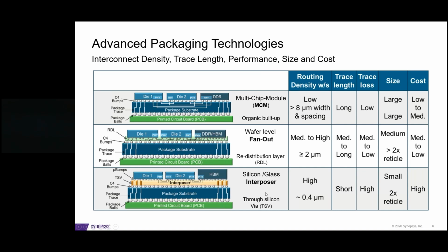And of course, silicon interposers provided. Question: the material for the RDL on that? So these are the RDL materials. These are post-fab, so these are not the silicon-based RDLs. These are the polymer-based RDLs, or the RDLs that are done after dies are already sliced and put in a carrier.